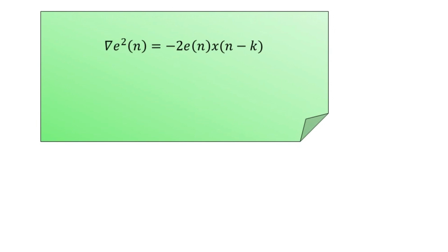So these rules are based on the premise that if the sign of the error signal multiplied by x of n minus k is changing frequently, then the coefficient W suffix n of k should be close to its optimum value where the gradient is equal to 0. So if the change of the sign is not observed to be frequent, then the coefficient denoted by W suffix n of k is probably not very close to its optimum value here. So therefore additionally we have hard limits placed onto the step size.